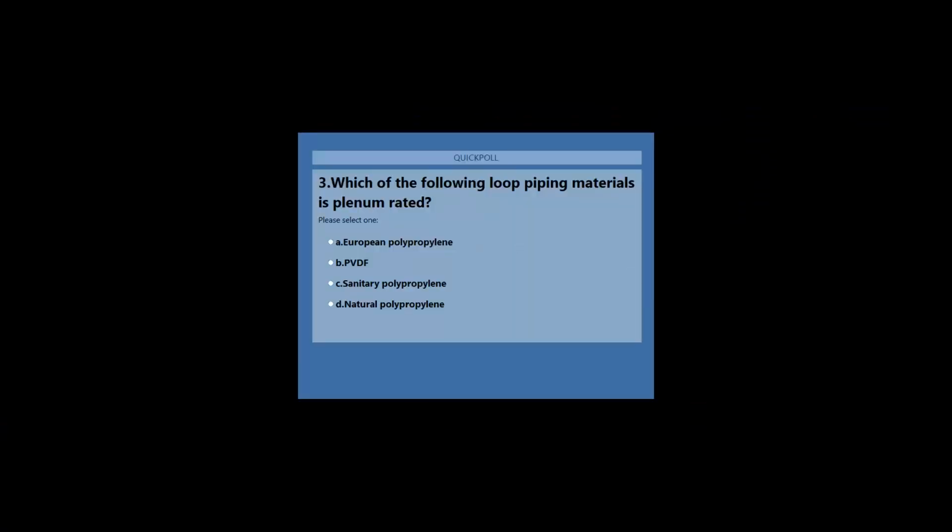And then finally, on the sanitary side of the system, you have both a natural and PVDF SIB or bead and crevice free. What this is basically, is a form of joining the pipe where you essentially have a diaphragm in your welder, which causes a very smooth weld within your actual piping loop to basically eliminate any of those rough surface areas caused by just either natural or socket fusion process. In pharmaceutical applications, you also see stainless steel. This is typically a polished stainless steel, which is also passivated and orbital welded, and that's used really predominantly only in the pharmaceutical industry at that point.